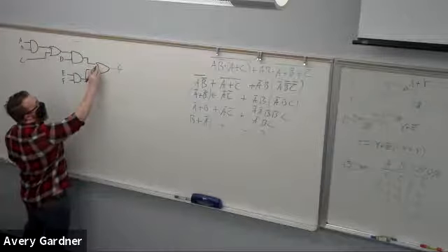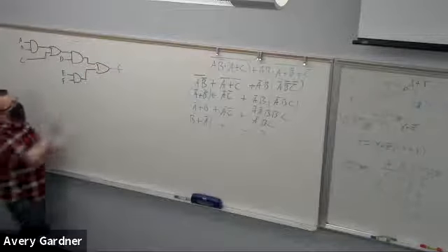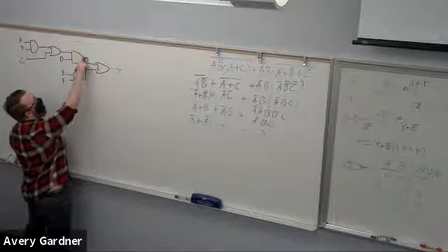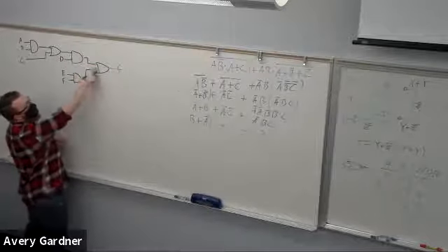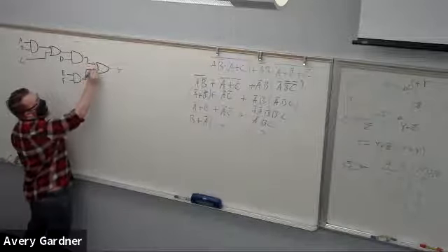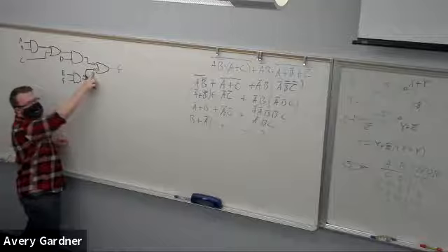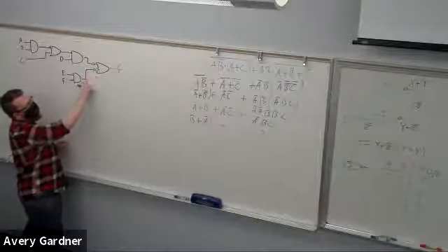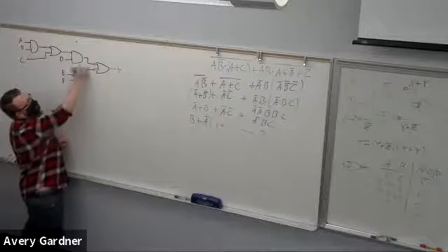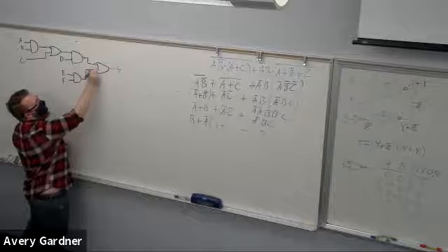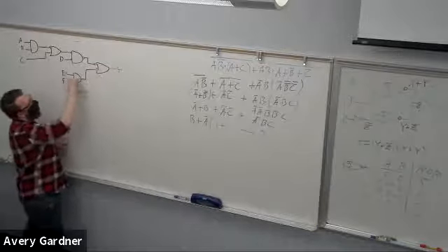So what I do, right, for a NAND gate is add some bubbles, and I may have been wrong on this one actually about needing the inverter, but I'll find out. And then I just push, right? So conceptually what I'm doing is I'm saying there are two bubbles right here. This is why I call it bubble pushing, because I'm undoing each of them. And then I just take this other bubble and push it all the way back until it hits these guys. So now that's a NAND gate. Those are NAND gates.